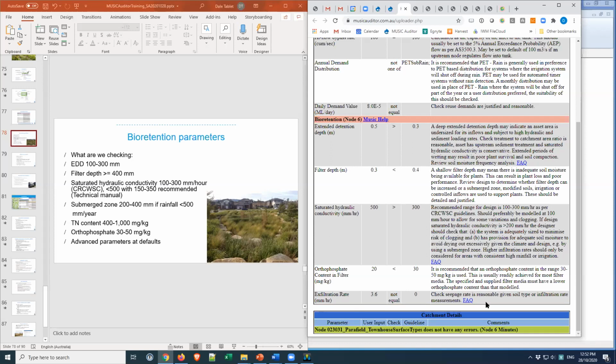And also have a think about whether there are any other geotechnical issues that might preclude you doing that: whether there's infrastructure nearby, whether there is high groundwater or saline groundwater, or there's a slope that you might be putting at risk. So if you're doing exfiltration at more than nominal amounts of 0.36 or 3.6, if that's 10 or 20, you definitely want to be looking very carefully at those geotech conditions.